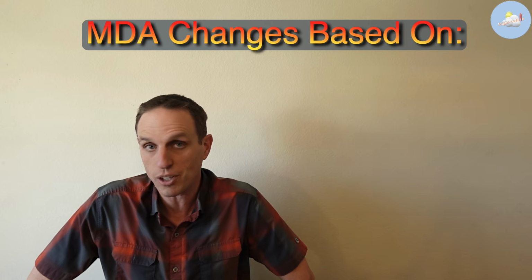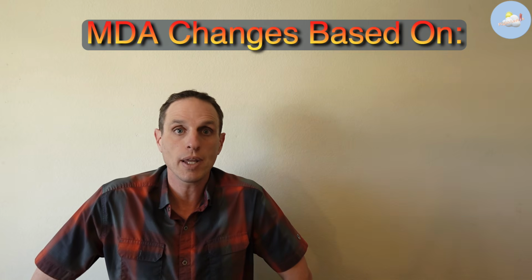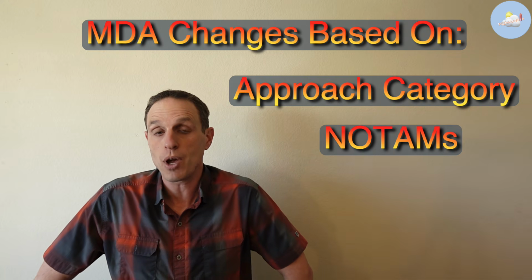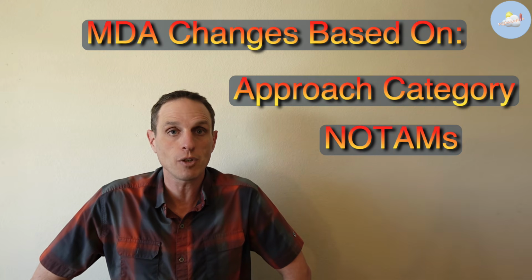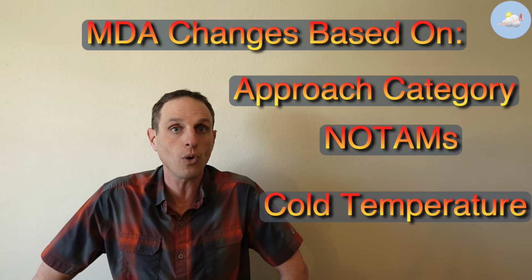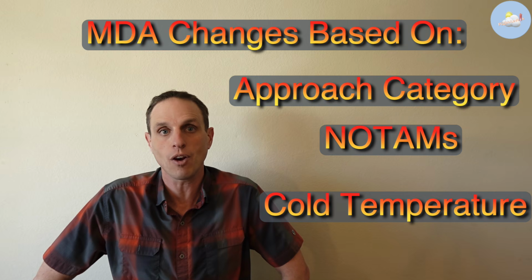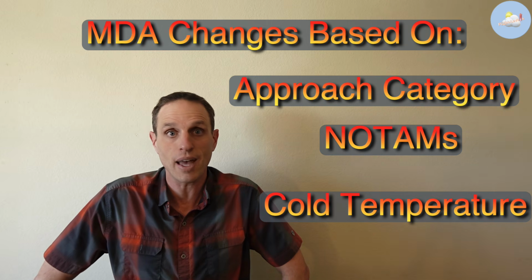Further, even if they wanted to make it level off at MDA, the MDA changes based on so many factors. The MDA is different depending on which approach category you're using. It changes based on some NOTAMs, and the MDA can also be raised as a result of cold temperature adjustments. So to assume that Garmin avionics are going to be able to adjust for all that is not reasonable.